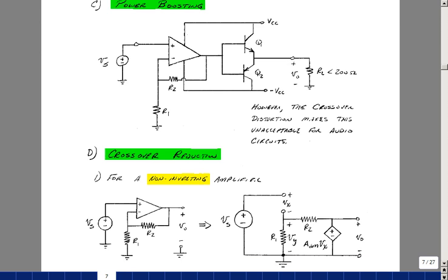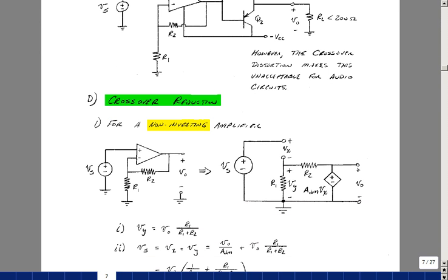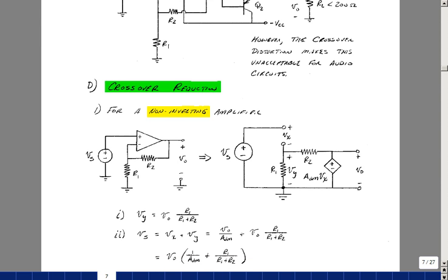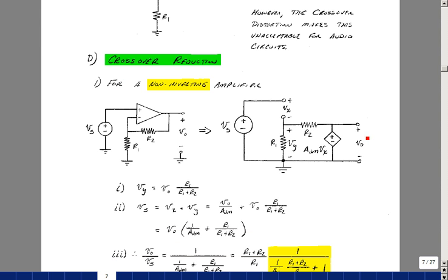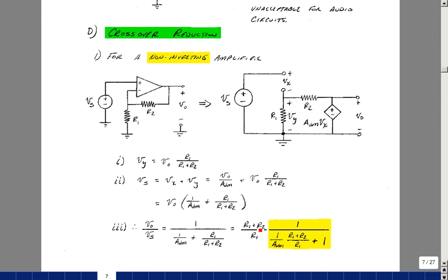So what we can do is use the idea of feedback and kind of go back to a derivation that we did in ECE 201, and that is taking a look at the output voltage versus the input voltage of, say, a non-inverting amplifier when we consider the fact that the op-amp is a voltage-controlled voltage source. Just repeating the derivation that's in the ECE 201 notes. But let me go over it again too here.